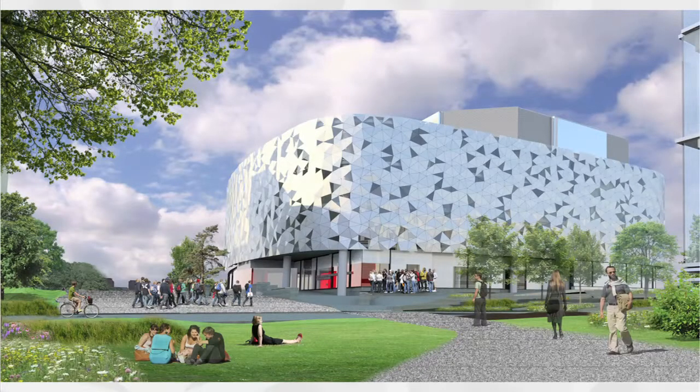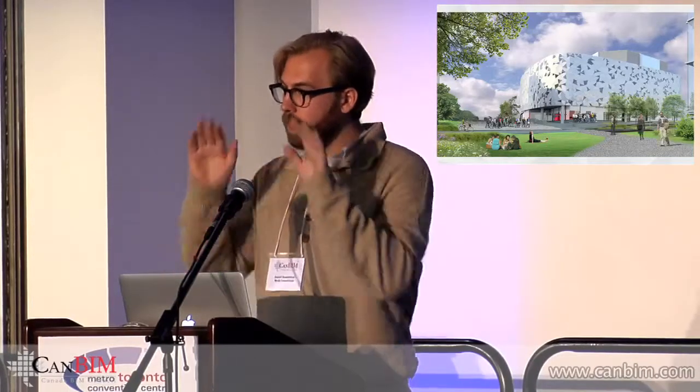More than that, because we now know exactly where all the panels are in space, although we've used the play between the panels to position them there, we know exactly where they are. And to assemble this system, you can grab one line that corresponds to a floor plate and precisely position one band of these panels. So maybe that might be 10% of the final thing. But the point is, because of their slight offset position, the rest of the structure is self-jigging. Every panel has to be one of these 3 types, so there's one position that the panel can fit given its predecessor. So this means that you can fairly efficiently construct these types of facade assemblies without having to laser scan every single panel.